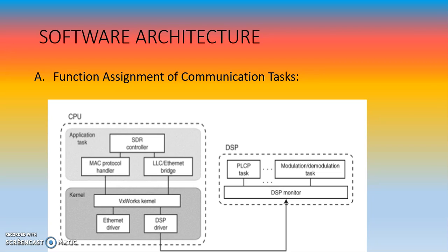In implementing the various IEEE 802.11 functions on the prototype, we assume that the MAC sublayer functions would be executed on the CPU, while the PHY functions such as modulation and demodulation would be processed by the DSPs. The PPP is used to perform the high-speed processing that cannot be run on the CPU or DSPs.